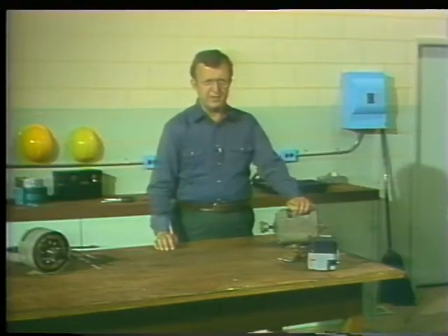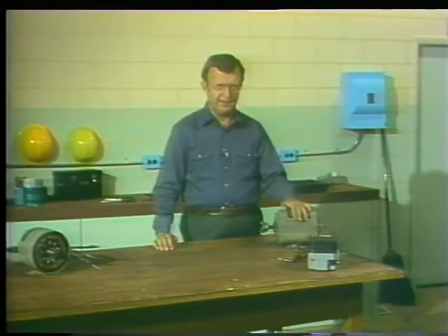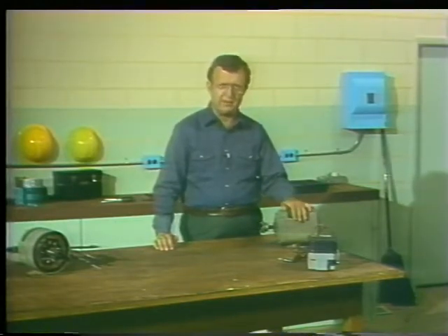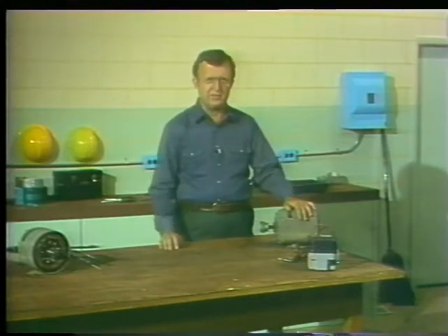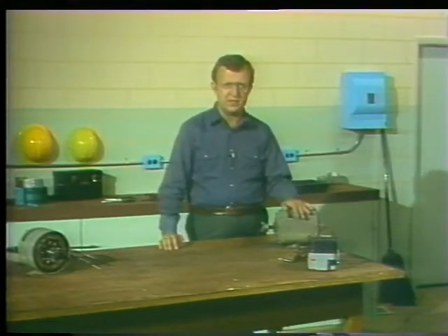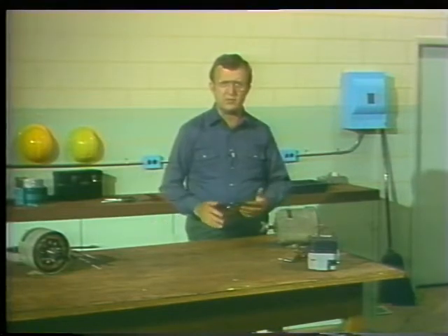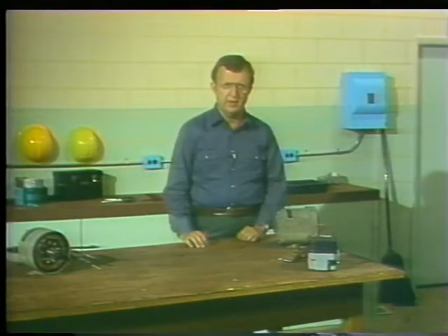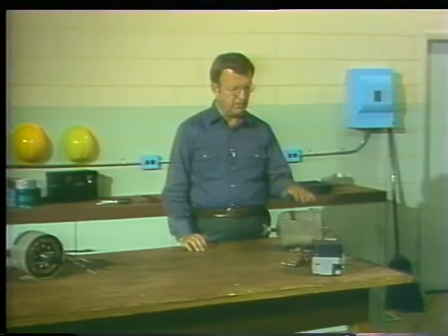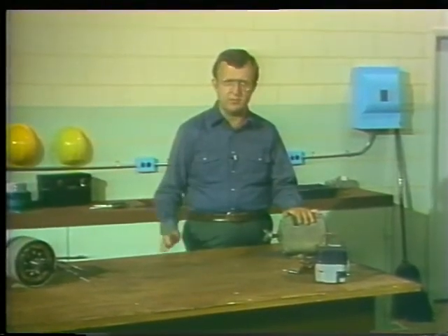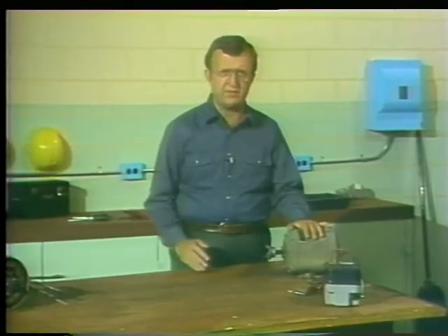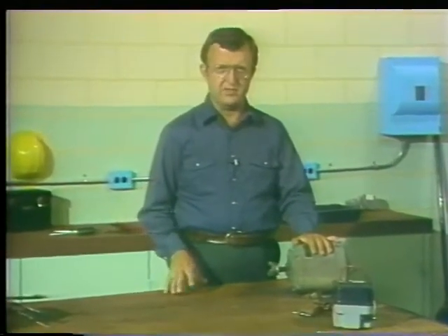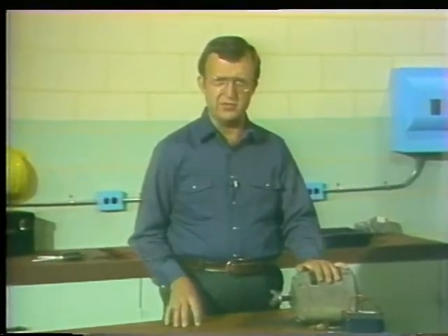Although preventive maintenance is important to keep motors running, it can't guarantee trouble-free operation. When a three-phase motor breaks down, it's your job to find out why. The best way to do this is to eliminate any of the possible causes of a motor problem. Often the problem won't be in the motor itself, but in the equipment the motor is driving or in the motor controllers. So do yourself a favor and check there first. You save yourself a lot of time and bother if you do.